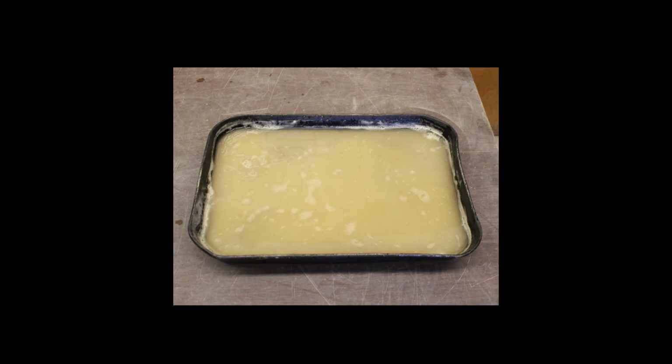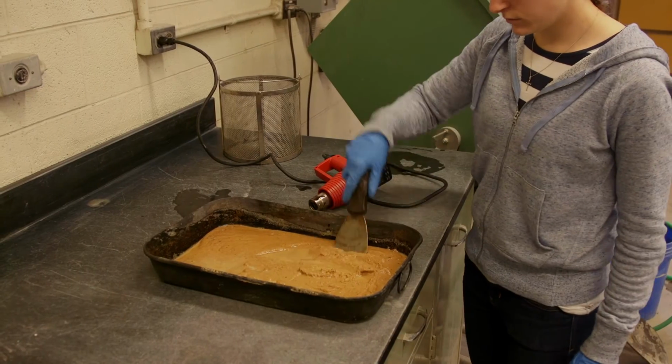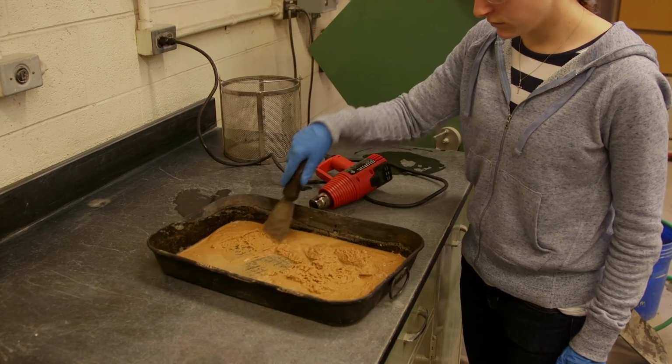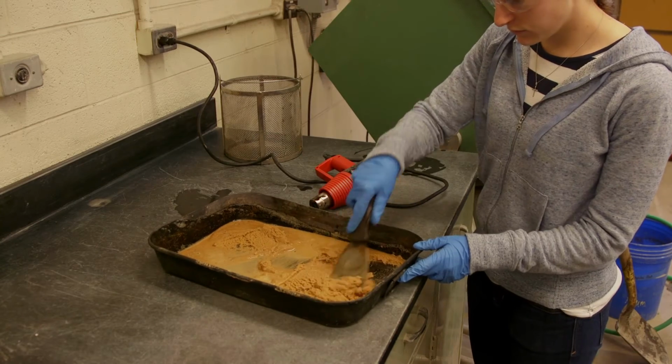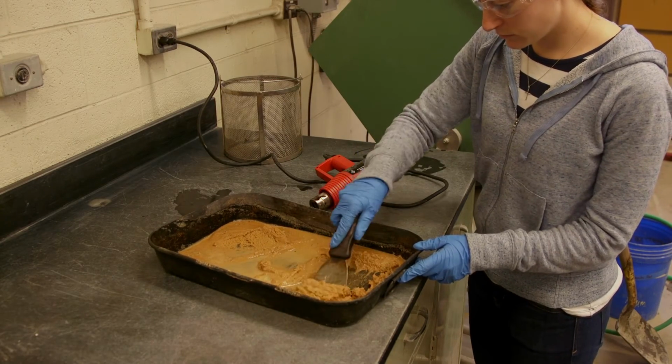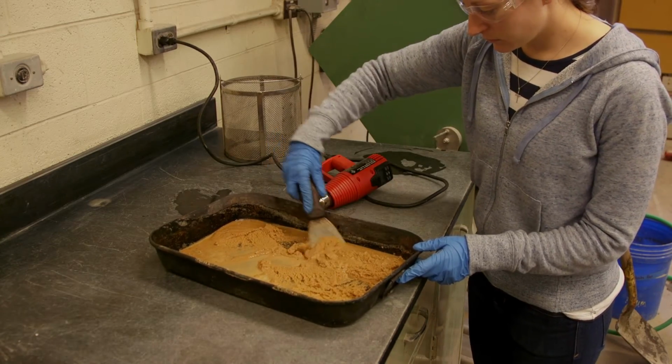Obtain approximately 1,000 grams of fine aggregate material passing the number 4 sieve. Immerse the aggregate in water at room temperature for a period of 15 to 19 hours. Dry the sample to a saturated surface dry condition. To do so, spread the sample onto a pan and stir it occasionally to assist in homogeneous drying.